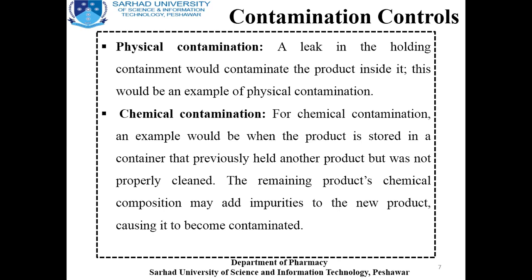I can say that during processing, if I am going to mix, and during the mixing the mixture is not properly cleaned and there are previous batch contaminants, particles or traces there, and I mix prior to approval of cleanliness, the SOPs are not properly followed, and the previous batch particles, that is the chemicals, get entered and become part of the new formulation or product, which is not desirable.